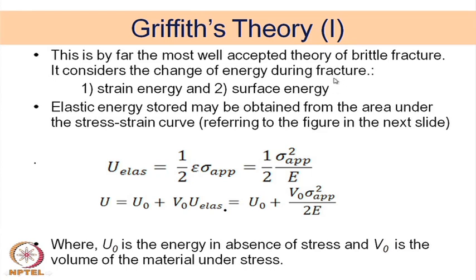We have earlier considered the surface energy term, but here we will also consider two different terms. One is the strain energy, the other is the surface energy. So, by applying a stress, you are actually increasing the internal strain energy of the system. And then also, if there is a fracture and a new surface is created, you have a surface energy term which is coming up.